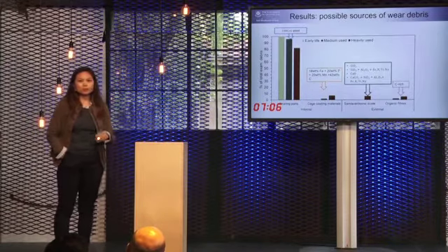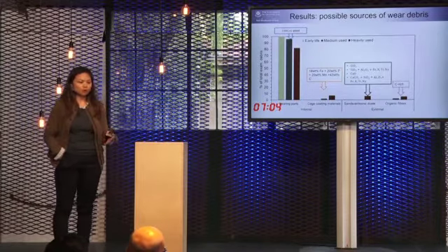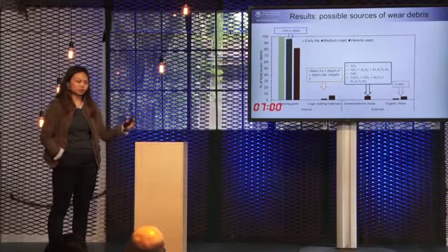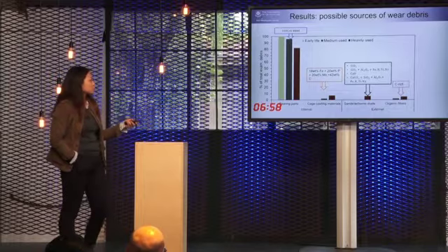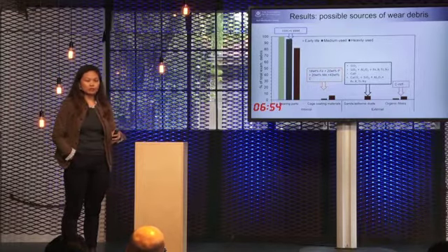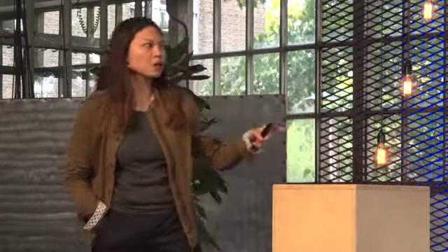When we talk about the possible origin of the wear debris, we found both internal and external wear. Most of the wear debris we collect from the used bearings is generated internally, which has a composition similar to the bearing particles or the cage coating material.